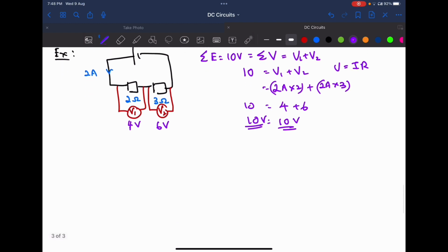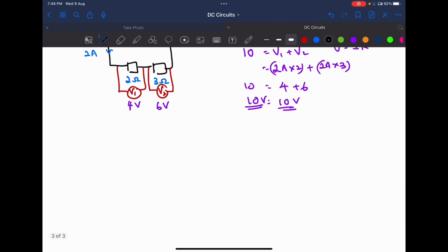Right? So if you are given a circuit something like this, EMF E1 and you have resistor R1 and you have another source of EMF, E2, and this is R2. Now the first thing you have to do is verify the terminals. This is positive, this is negative, positive, negative. That means the current is traveling in this direction.